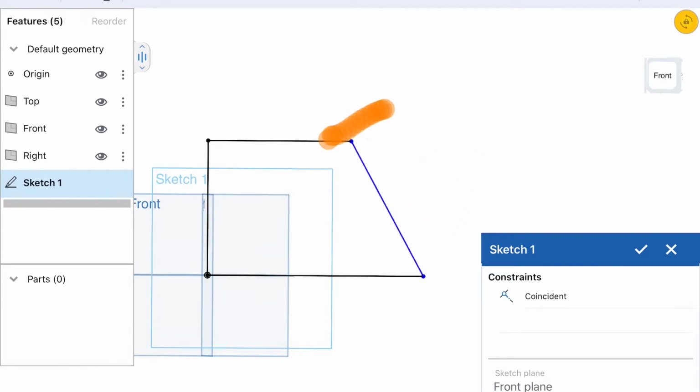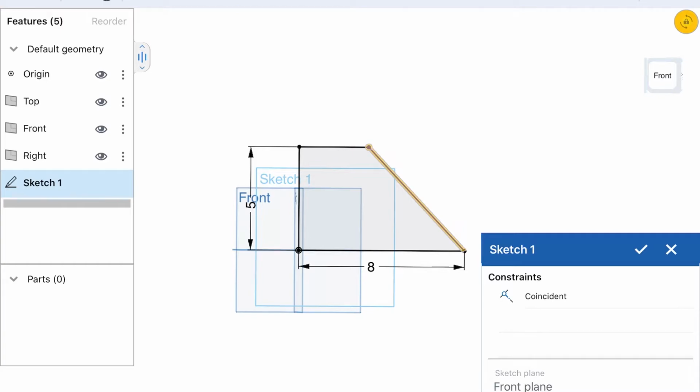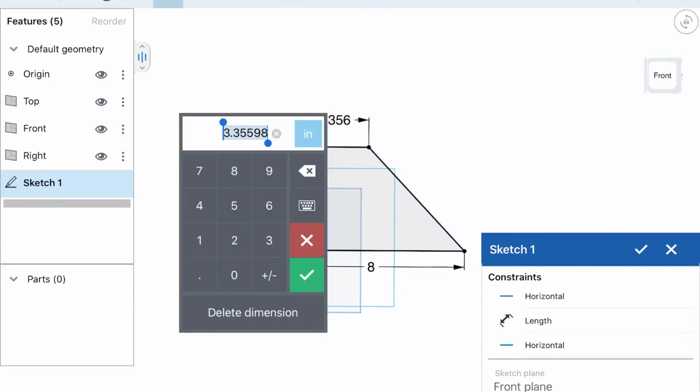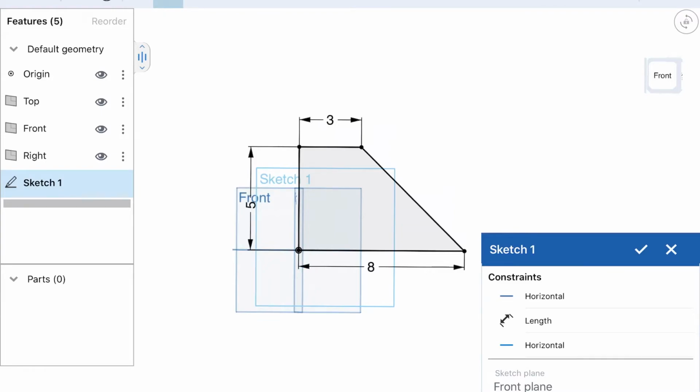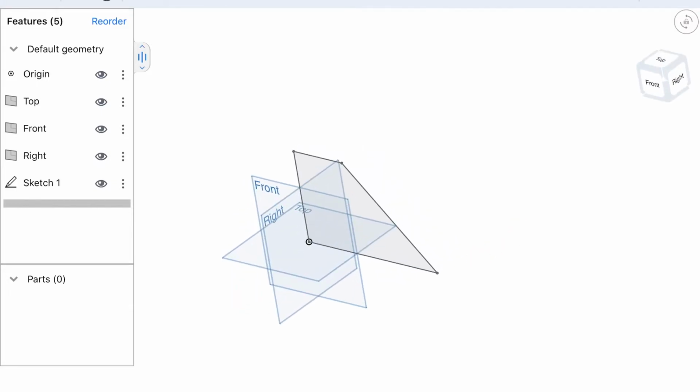I don't think that point, the point's still movable because I didn't dimension that top side. So if I dimension that, that should be 3 units. Perfect. Okay, now I have it dimensioned the way I need it to. It's all black. Alright, so when it's all black, it's all fully dimensioned, and so then I have my sketch.